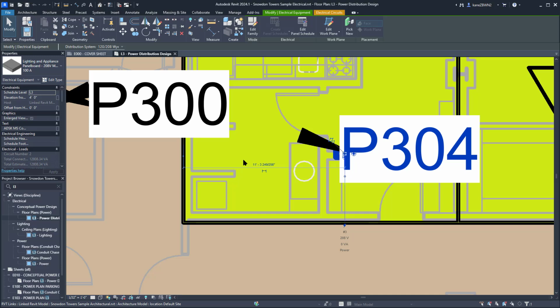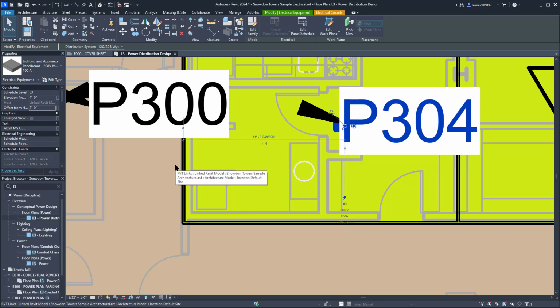For things you can change, select the value, make the change, then, and this is the important part, move your cursor off the palette. Revit interprets that cursor movement as you saying, I'm okay with this, save my changes, and update the model. I'm also mentioning that so you'll know what's happening if you're ever trying to change something. You move the cursor so you can see what you're typing, then it deselects the property before you're finished typing.